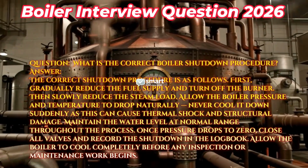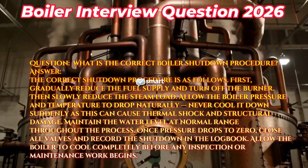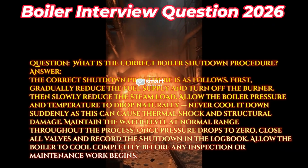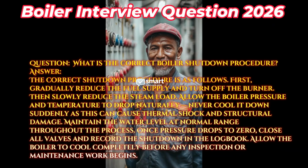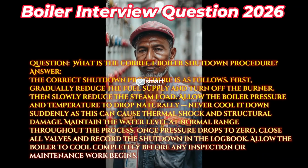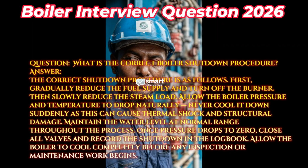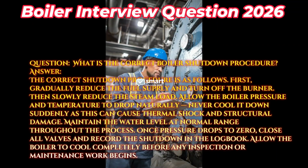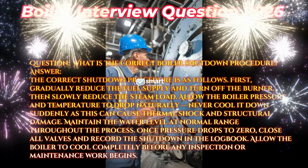Question: what is the correct boiler shutdown procedure? Answer: the correct shutdown procedure is as follows. First, gradually reduce the fuel supply and turn off the burner. Then slowly reduce the steam load. Allow the boiler pressure and temperature to drop naturally. Never cool it down suddenly as this can cause thermal shock and structural damage.